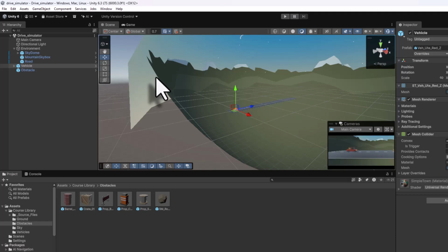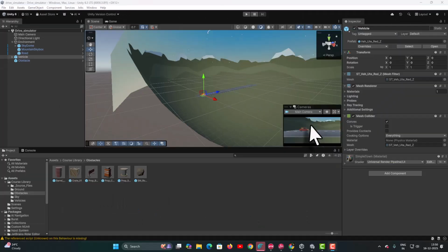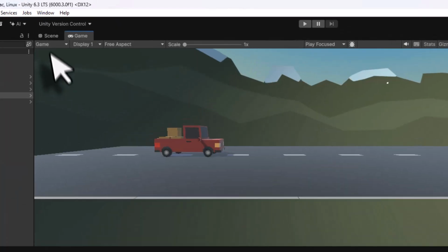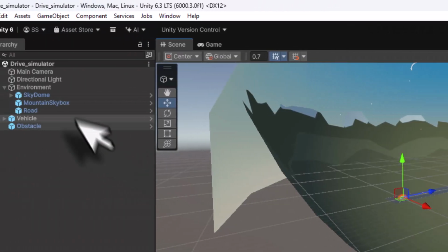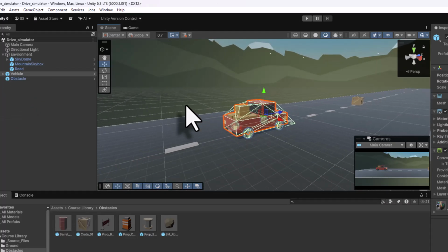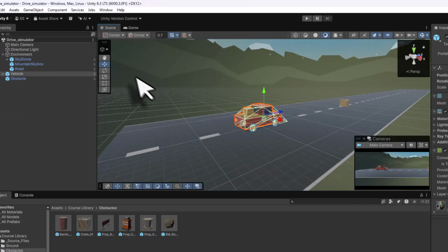So that's why in our previous session, when I clicked the play mode, we had added a red color overlay so that we know that the game is in play mode. If you see the camera in the game view, the camera is on the side. We are seeing our car from the side. But for my game, I want this camera to be on the left behind this car. That is, if you come into the scene view and if I select the vehicle, press F to zoom, I will slightly zoom out, and I want the camera to be placed on the back.